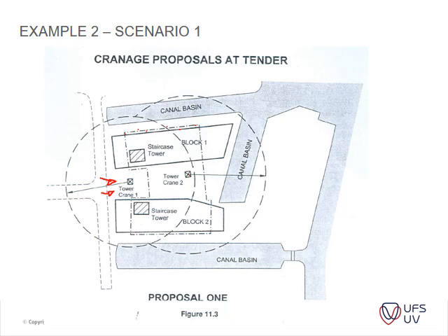Okay, are you guys comfortable with that? So it's just a method statement. This is how they thought about it. The 20-meter radius reach is not really necessary. There's something which I don't say here, that one should also consider is regulations. Is how far a crane can actually reach over a public road and into someone else's site. So that's something that one needs to consider as well.